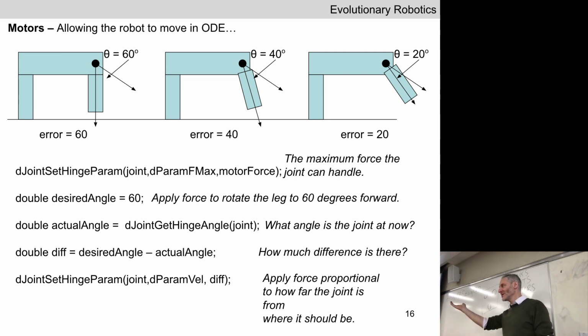And then the physics engine takes over from there. It updates the positions and orientations of the links, given that additional force that the motor is applying to the links through the joints. Let's imagine at this particular point in time, at a particular time step in the physics engine, the robot's front leg is off the ground, its back leg is on the ground.